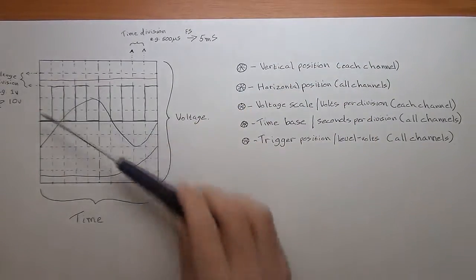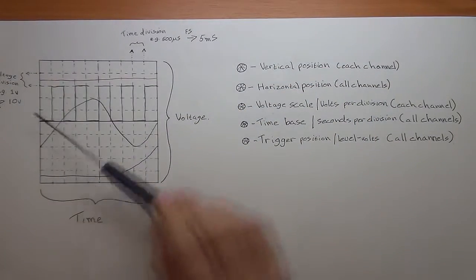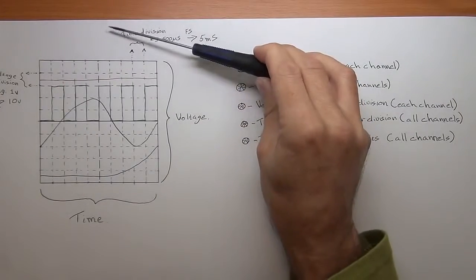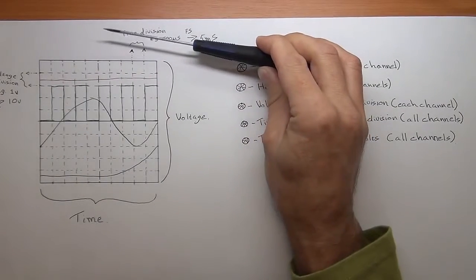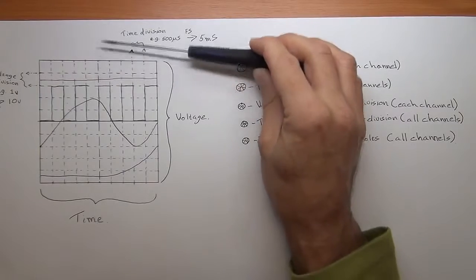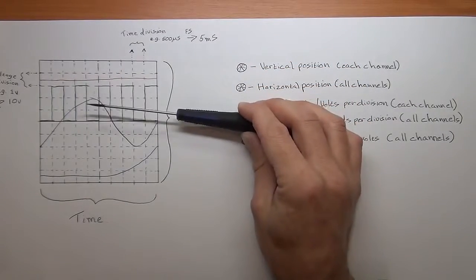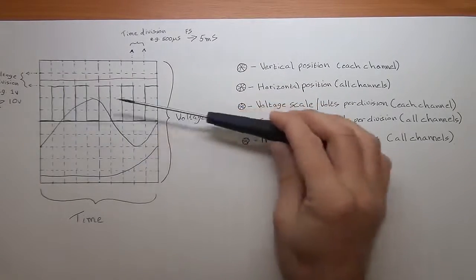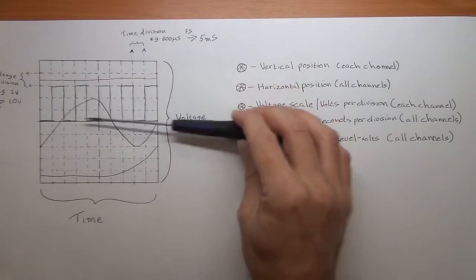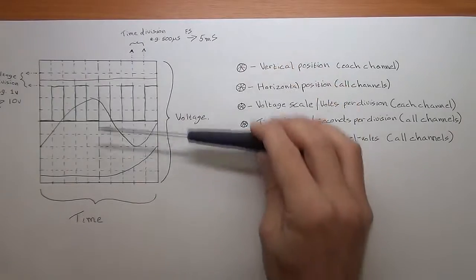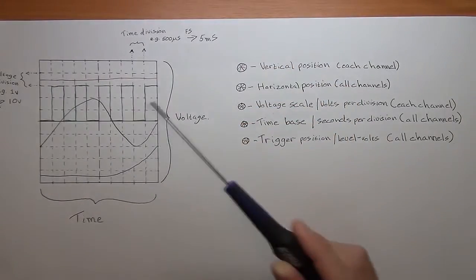Depending on what scale you've set for your oscilloscope, it might be out of range of the display. As you saw, I had that signal from the battery and I had to pull it down so it was in range of the display and of the measurement values I had pre-selected so that I could see it. And that's the vertical position knob. Very, very simple to use.